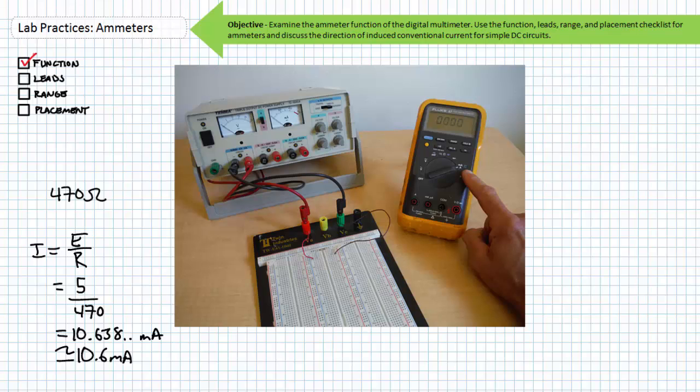The Fluke 87 also has a microampere mode next to the milliampere/ampere mode if it is your intention to measure extremely small values of expected current. For both the milliampere/ampere mode and the microampere mode, there are two different flavors of current: DC versus AC. DC is the straight line, AC is the squiggly line. The Fluke 87 defaults to DC ammeter mode and indicates so by placing the letters DC in the display.